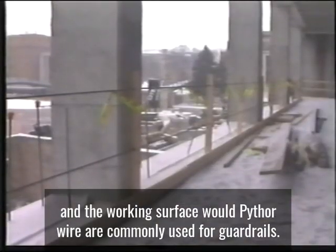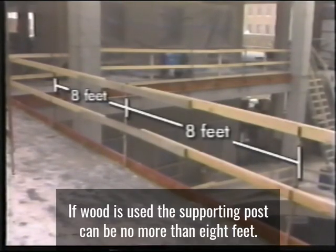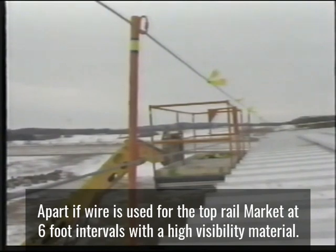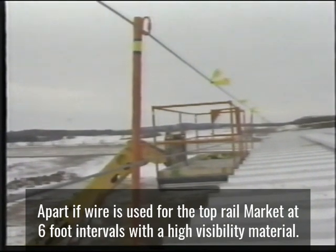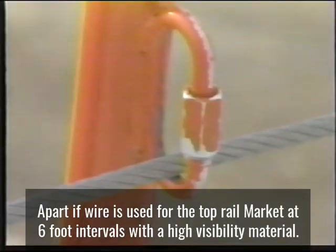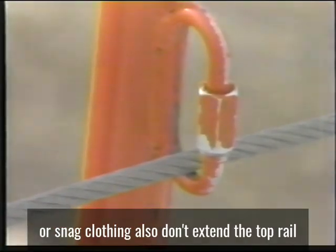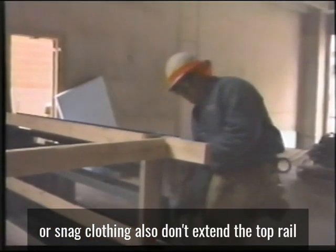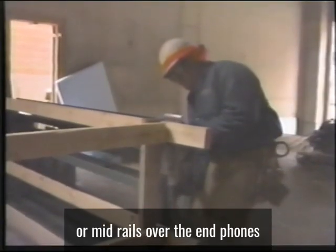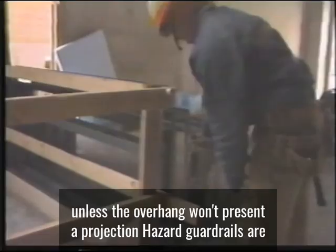Wood, pipe, or wire are commonly used for guardrails. If wood is used, the supporting posts can be no more than 8 feet apart. If wire is used for the top rail, mark it at 6-foot intervals with a high visibility material. This wire must also be at least 1/4 of an inch thick so it doesn't cut the skin or snag clothing. Also, don't extend the top rail or mid-rails over the end posts, unless the overhang won't present a projection hazard.